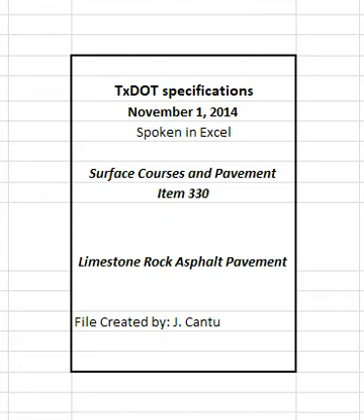4.4.2 Tack coat. Clean the surface before placing the tack coat. Apply tack coat uniformly at the approved rate, unless otherwise directed. The engineer will set the rate between 0.04 and 0.10 gallons of residual asphalt per square yard of surface area.